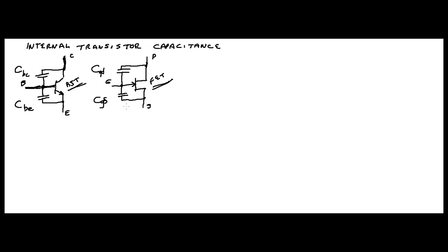Similarly, you're going to have capacitance between your gate and your drain. So it's going to be CGD. That's a D there, I'm sorry about that, it should be a capital D. I thought it looked like a P for a second. But anyway, that's C, gate, drain, and you also have capacitance between your gate and source. Here's your gate, there's your source, so it's CGS.